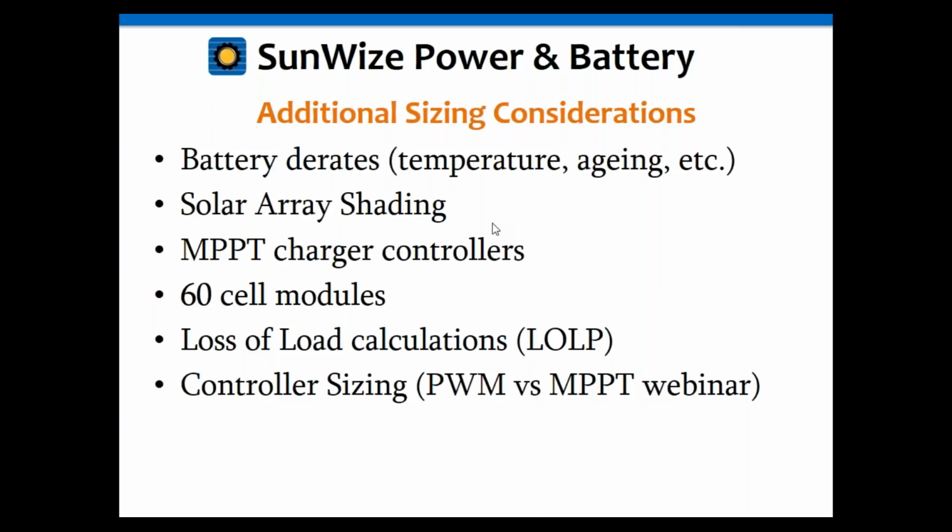There are a couple of differences. The main one is the plates themselves. In a car battery, you're going to have thinner plates, but more of them. So you have more surface area, so you get a lot of current off of them for starting a battery. It's where you get that cold cranking amps from, so they create a lot of surface area to get lots of current. The problem is that when you do that, because the plates are thinner, they don't want to cycle very deeply because the plates are very delicate. So in a deep cycle battery, you're going to find there are fewer plates, but they're thicker, so the plates are more robust and can take more abuse in the deep cycling.